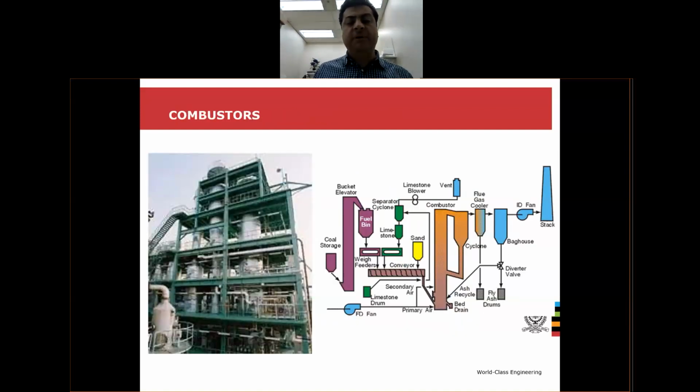But another type of fluidized beds are for combustions, either coal combustion or biomass conversion. For example, consider this fluidized bed reactor. You can see that in this case, coal is prepared and then mixed with limestone, and then by a screw feeder is injected to the bottom of the fluidized bed reactor.